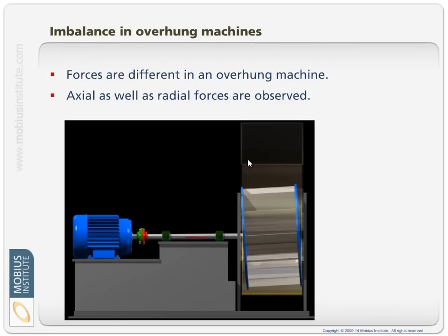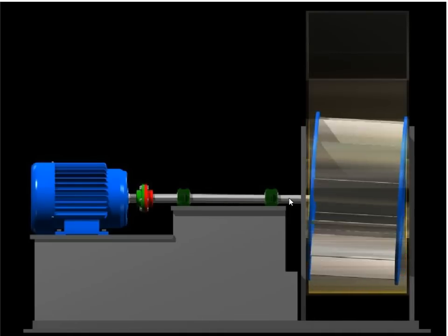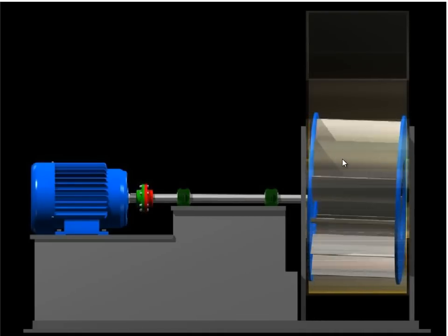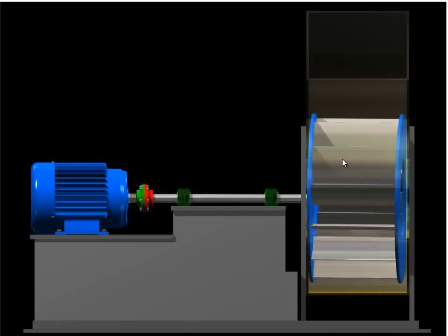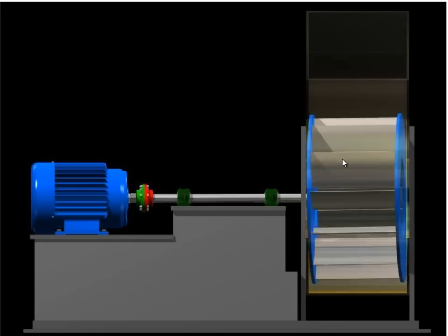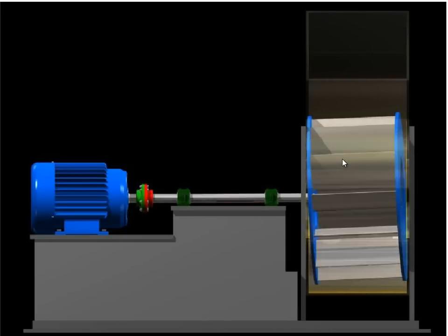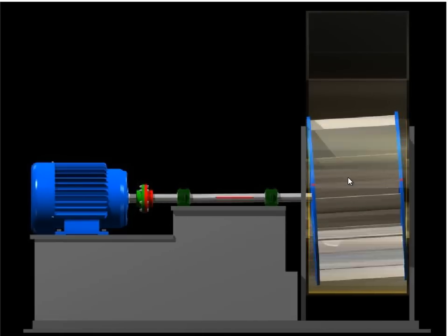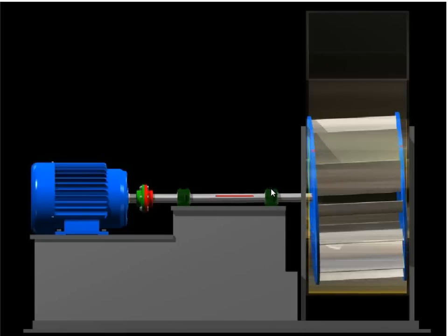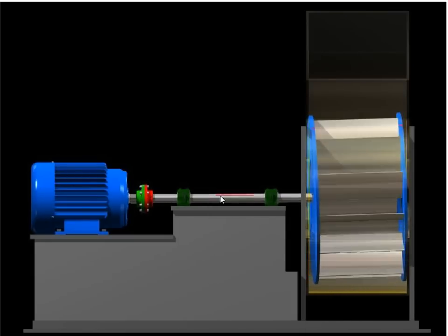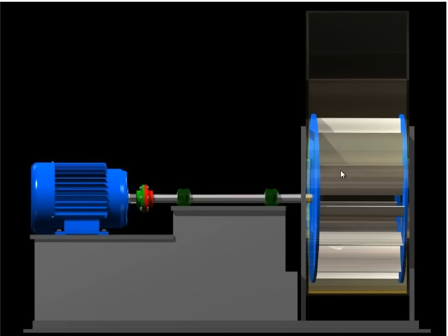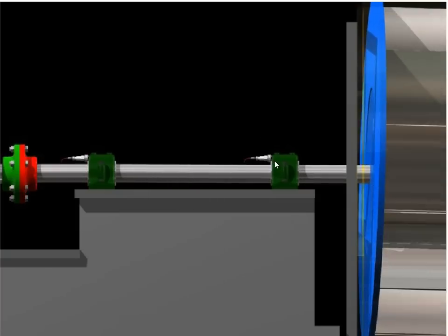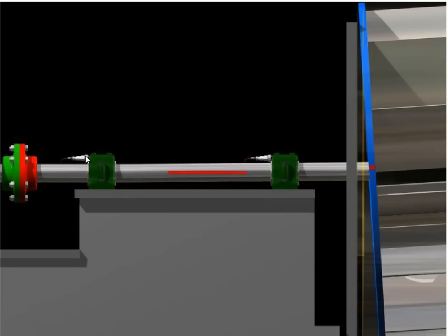If I have an overhung rotor, not only do I get the circular motion that we just saw, but we also get a rocking motion. Let's have a look. So I'm not just showing the radial centripetal forces, I'm focusing on just the rocking. And once per revolution it sort of rocks back and forward, if you like, as that overhung rotor flexes due to the out of balance on these blades. So it's still circular motion, so our 90-degree rule applies here and here, but we create axial vibration as well. So we measure that and we look at the phase reading. So we put our sensor axially and see what happens.